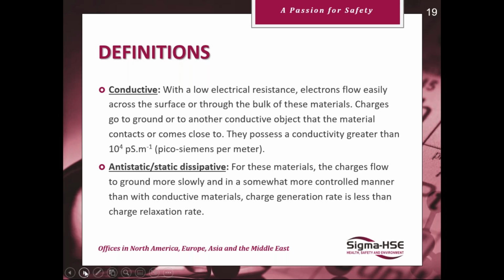Anti-static, static dissipative. For these materials, the charges flow to ground more slowly in a controlled manner, unlike conductive materials. Charge generation rate is less than the charge relaxation rate. In other words, you get rid of the charge faster than you can build it up.